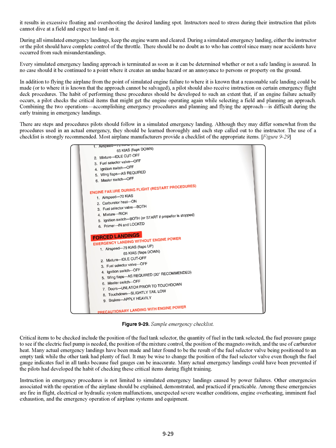Many actual emergency landings have been made and later found to be the result of the fuel selector valve being positioned to an empty tank while the other tank had plenty of fuel. It may be wise to change the position of the fuel selector valve even though the fuel gauge indicates fuel in all tanks, because fuel gauges can be inaccurate. Many actual emergency landings could have been prevented if the pilots had developed the habit of checking these critical items